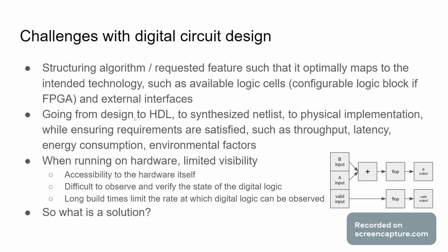Just doing a build. Unlike regular software where you compile the code and it runs in a processor and it executes like one instruction at a time, basically, when you build an FPGA design, you start with an HDL, which are like the programming languages for digital circuit designs, hardware description languages. Those get synthesized into a netlist. A netlist is composed of the primitives, which are usually LUTs and flip flops, and those need to get placed into the physical part and then routed together.